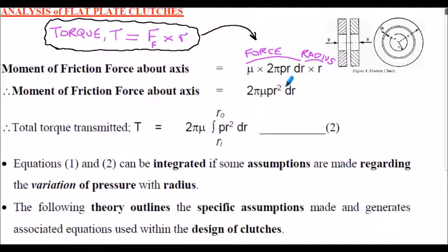So from that, we can work out the torque on that ring. What we're effectively doing here is having a frictional force. I'll just draw it over here on the ring. There's a frictional force. It doesn't matter where I show it there if you like. There's a frictional force applied here, which is our FF. And that multiplied by the radius from the center of rotation will give us a torque. So that frictional force on that elemental strip, FF, multiplied by the radius of that strip, which is this radius shown here, will give us the torque from the elemental strip. And that's all I've got here.